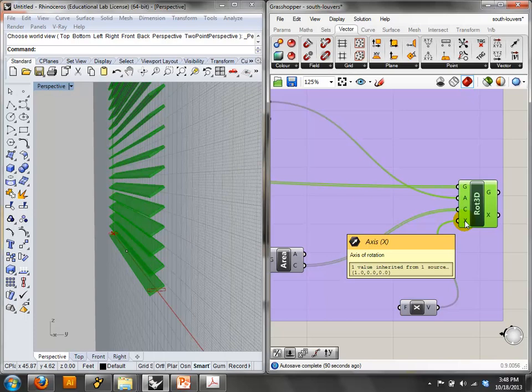So would you have to evaluate your form? You can do that, yeah. How would you find an edge of that rectangle to use it as the hinge? Okay, so if it's the rectangle, I could take the form that I created and do a Brep explode. I could get into the data structure, find out what that point is and what the other counterpoint is, draw a line with them, and then plug that in for my axis. Conversely, if I wanted to rotate it this way, I would just find these two points. All I need to do is draw a line. If you can extract a line from your form, you've got an axis. Yeah, that's a great question.